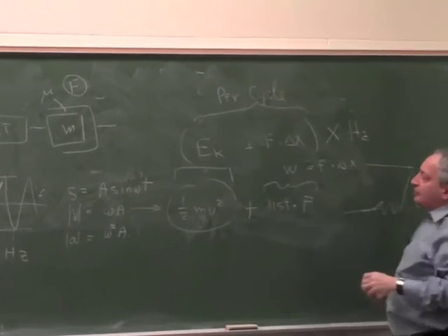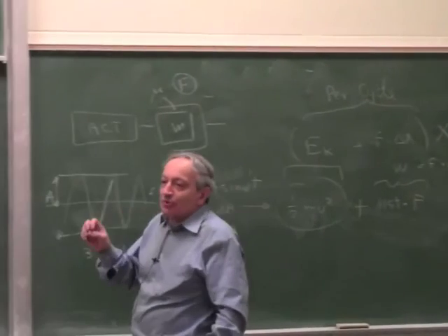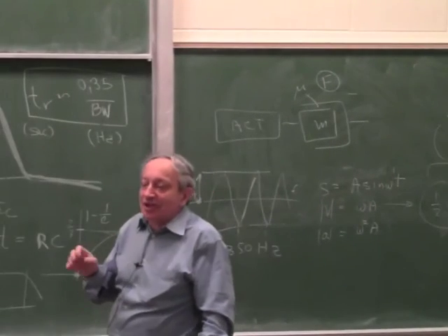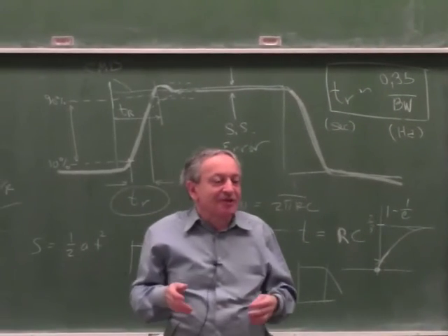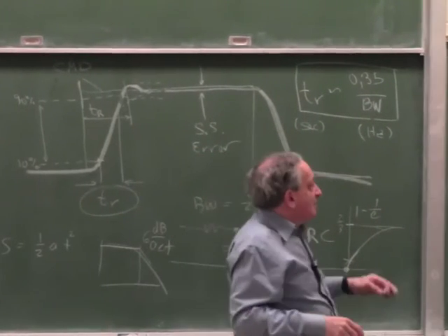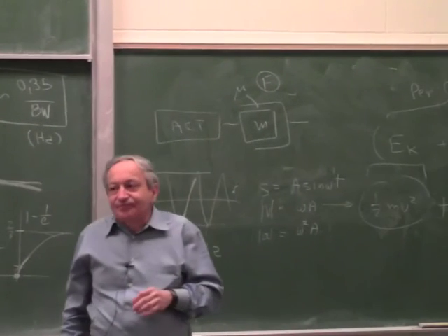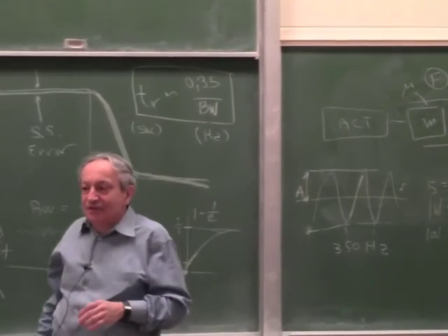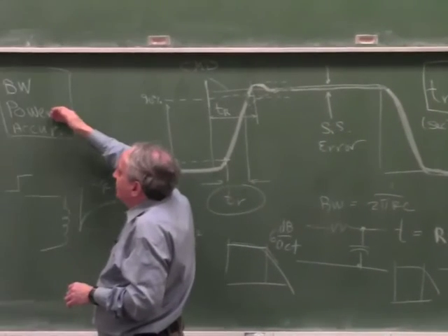So it's a very crude way to look at it, but that's good enough, because you are not going to choose a motor just marginally. You always choose an actuator which has some safety margin. So this gives you an idea how much energy the system needs. So now you know the bandwidth, you know roughly the power you need.